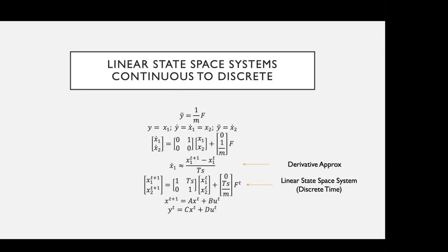So if we go back to this system here, we can look at the A matrix, and when we look at the eigenvalues, we can immediately tell whether our system is stable or unstable based off of the eigenvalues.